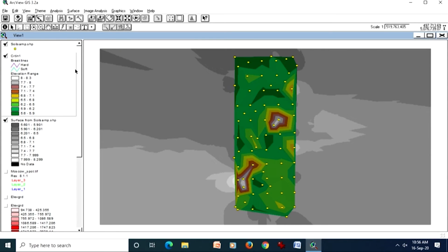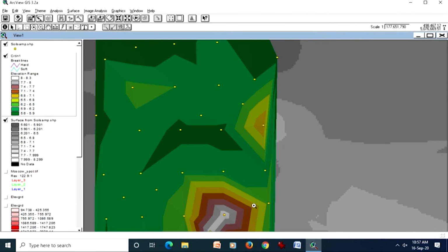Each mass point, each point, is used to create a triangle, or rather instead of calling it a triangle we can call it a facet. Even in this case, if you see here, this is one point, this is one point, and maybe a little lower. So here no extrapolation, this point, this point, this point has been used to create a triangle. Recall our Delaunay theorem, which says that a circle should be drawn in a manner that only 3 points it should connect, not any other, and then that triangle is formed. So this is how these facets are formed.